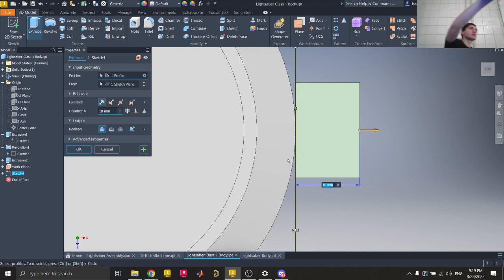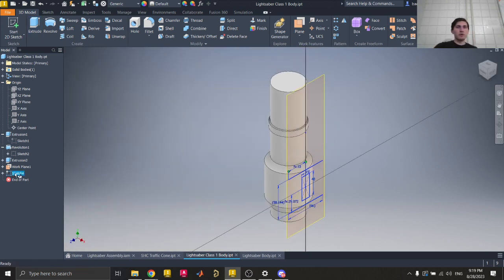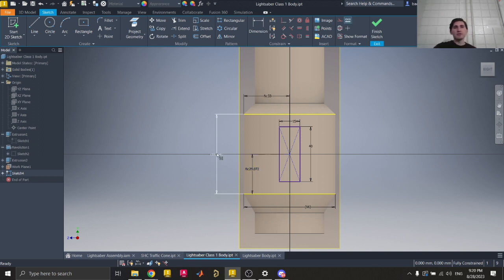Question? How did you center D18? I don't know which one. Yeah, so all I did was, whatever your vertical or your horizontal dimension is, you can just double click it to where you go to type in a number. So for this one, this one is for the vertical centering. So I have this reference dimension right here that I made that's just the dimension of top to bottom of this section. All I did was I just selected it and then typed in divided by 2. And then check mark, yeah.